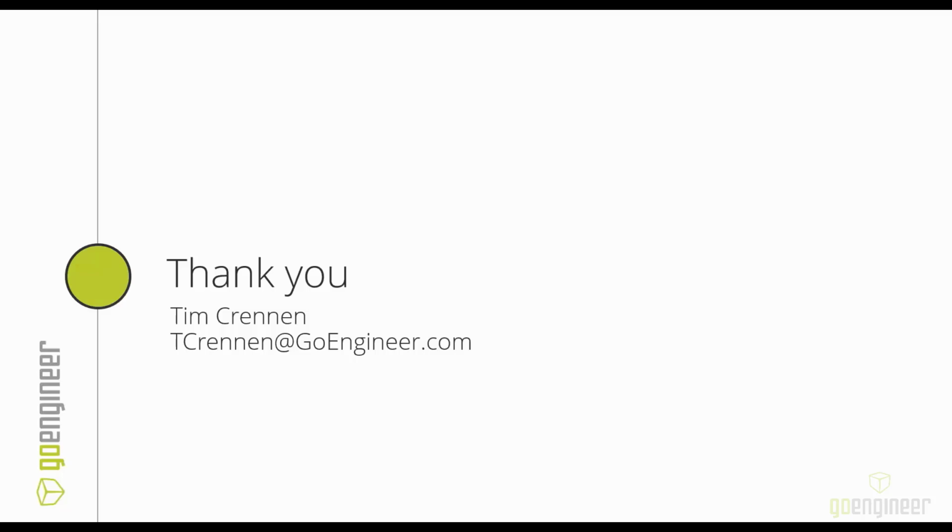And you also take in a couple other things for designing it, like gate placement. You don't want your gates to be going at as high of pressure, so you might want to make them a little bit bigger, make them not point at thin features, and not go through just one gate. If you can spread out to more gates going into your part, that helps reduce the pressures and helps prevent distortion and degradation of your molds as quickly.